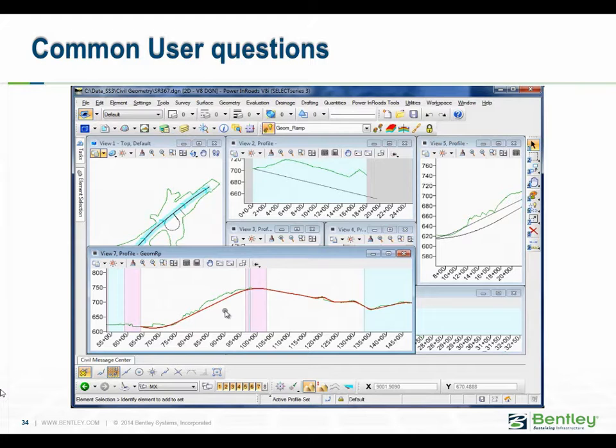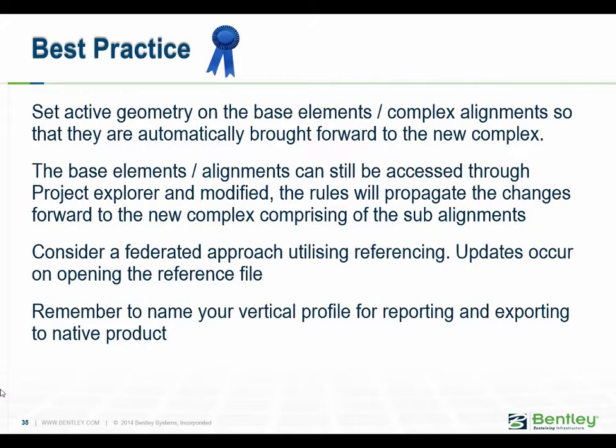It's just an example of design intent being part of the command: you can design individual profiles, and when you complex the alignment, it maintains that relationship to the individual profiles. Summing up, it's not really a simple example, it's quite complex, and it deals with reversing of elements, setting active profiles and propagating them forward, but it shows the complexity and intelligence that you can achieve.